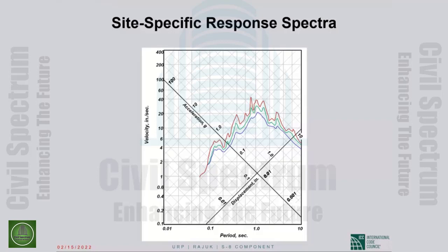This entire field of earthquake engineering is full of uncertainties. If there is one certainty, it is that an earthquake that has hit your structure in the past will never hit it again in the future. A structure will never ever see the same earthquake twice. That being the case, it does not make any sense to design a structure for a particular response spectrum of a recorded earthquake.